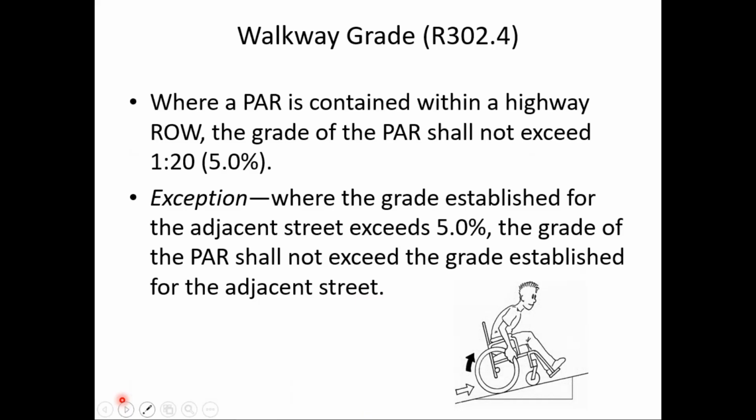Walkway grade. Where the PAR is contained within the highway right-of-way, the grade of the PAR shall not exceed 5%. That's what PROWAG says. In fact, that's what ADAAG says as well for grade. But there's an important exception in PROWAG. Where the grade established for the adjacent street exceeds 5%, the grade of the PAR shall not exceed the grade established for the adjacent street. So if sidewalks follow the street, or I like to say if the sidewalks serve the street, they can follow the same grade as the street grade, even if that's well in excess of 5%.